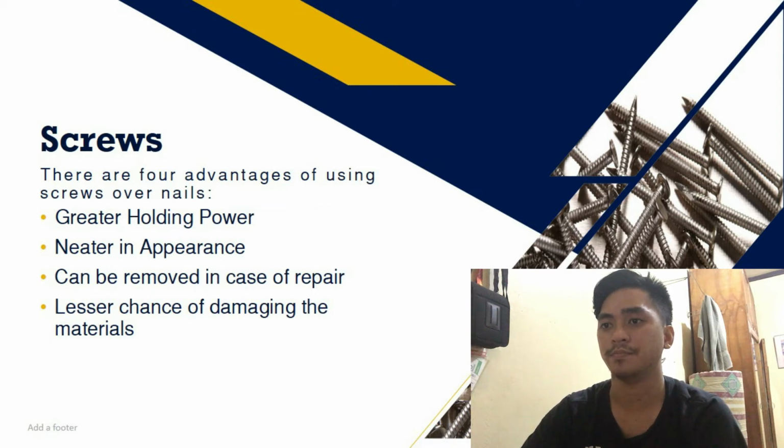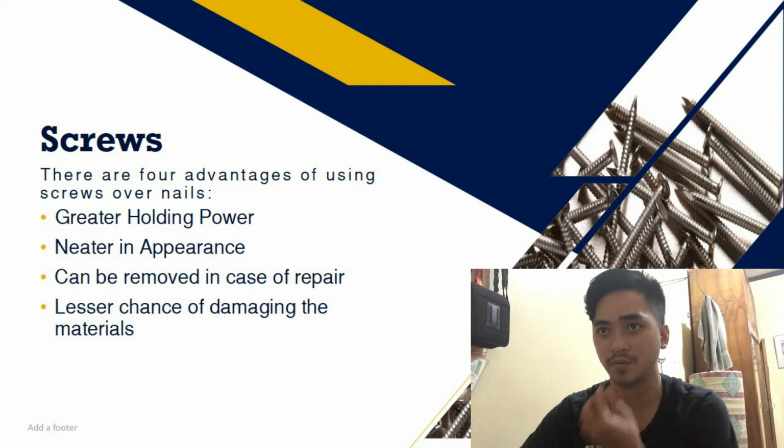So, there are four advantages of using screws over nails. First, it is greater in holding power. Next, it is neater in appearance. Next is that it can be removed in case of repair. And lastly, it has a lesser chance of damaging the material.